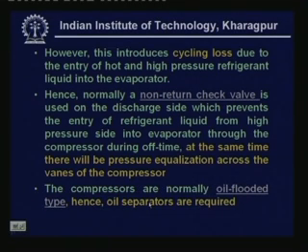The compressors are normally oil flooded type, hence oil separators are required. As I said, sealing is required between the various leakage paths, and normally the sealing is achieved by using hydrodynamic lubrication. That means lubricating oil is used to seal the leakage paths. Okay, so let me show this.